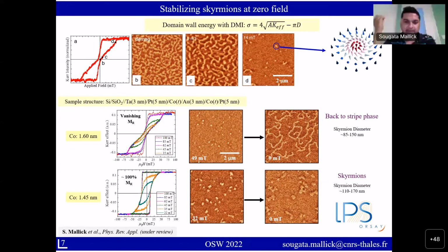The direct answer to this question is that I don't check the resistance of my track during the measurement, so I cannot really comment on whether it is changing the resistivity of the total stack or the heavy metal. But what I can tell you is that I always check the resistance of my track after applying one pulse, just to check if it has damaged my track or not, and the resistance usually remains constant. So in the equilibrium state, after we apply the pulse or after we take the measurement, the resistance does not vary significantly.